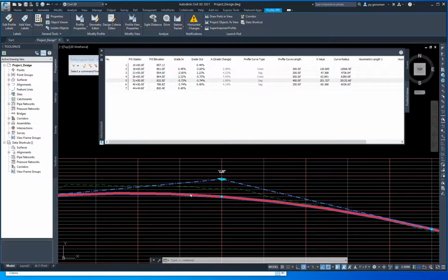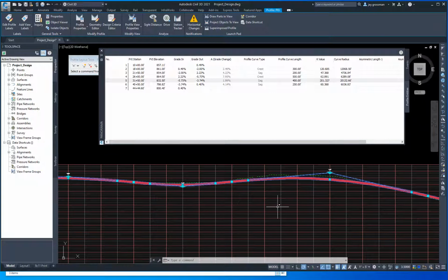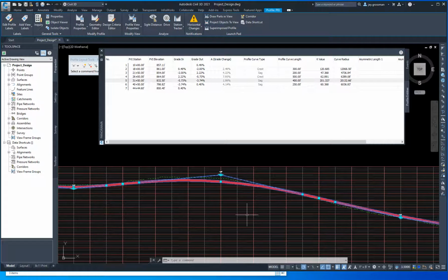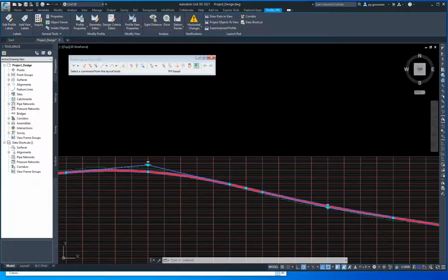And that's really it. You've just now designed a road. And now you're going to go through and check your design criteria. You're going to make sure that your up and down tangents, your max and min grades are met. You're going to make sure that your K values are met and so forth. Right. And then we're all good. And we can close this window when we're done.